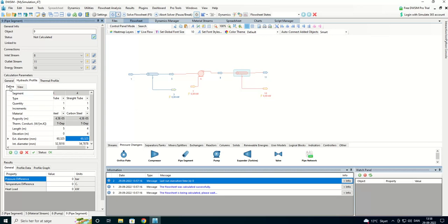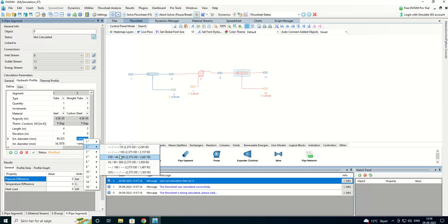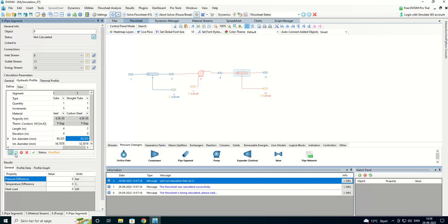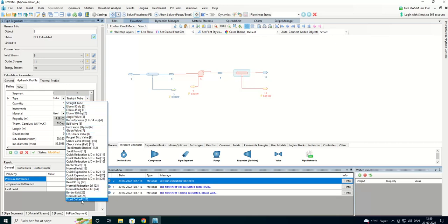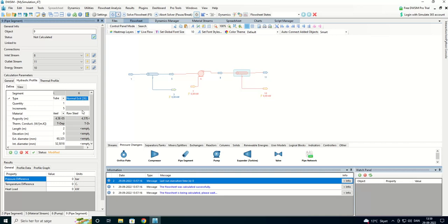And then we have to add the last 2 meters of pipe, with 0 meters in elevation and the tube diameter. And we also had to add an outlet, because that is also giving some pressure drop.